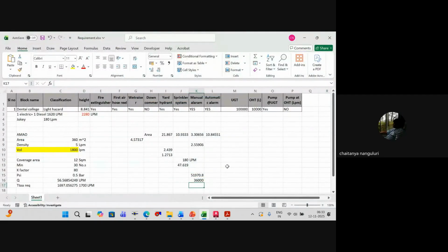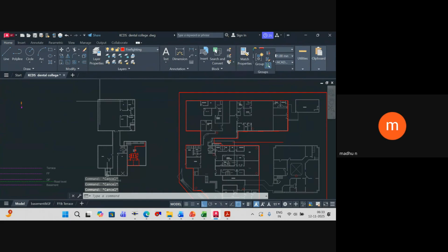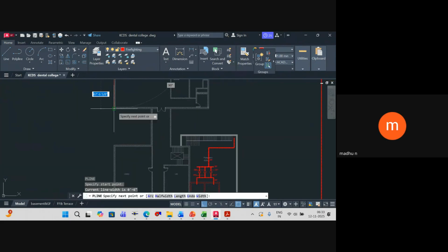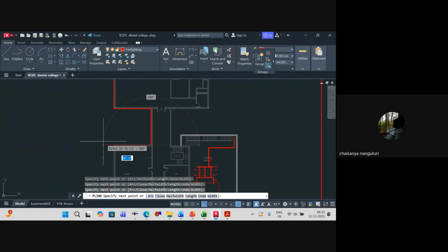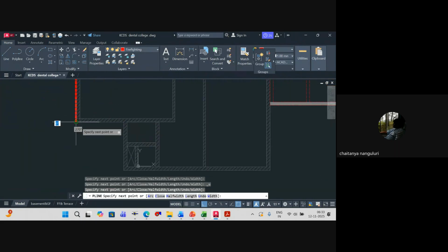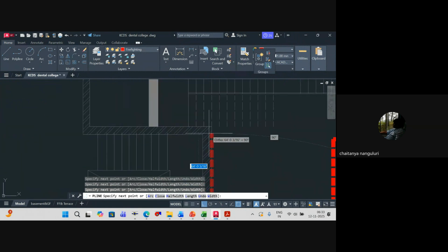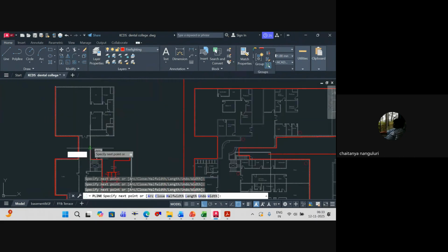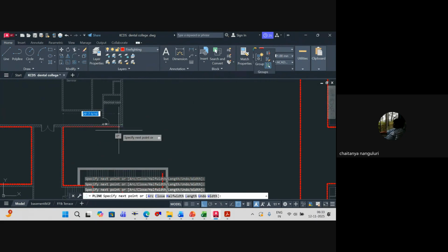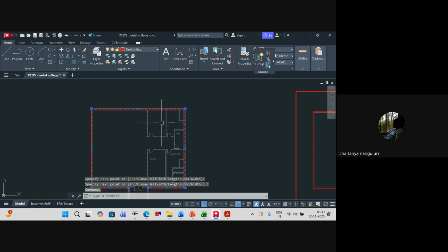So if you take it, probably I will require this into 2, is 72,000, plus we have to take this area also. Around 15, just a second. Pump room is probably not required because if the area is lesser than 200 square meters, then it's not required to have a sprinkler system. Moreover, it's completely external, so it's not mandatory.